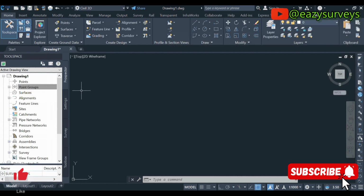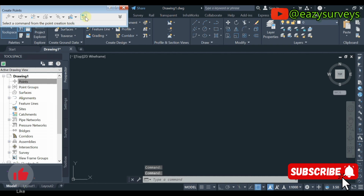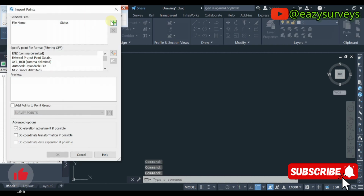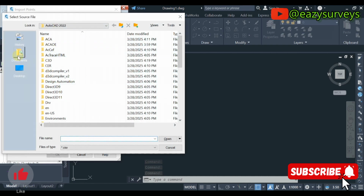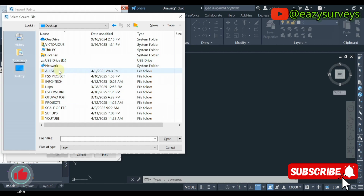Then the next thing is to import your survey points from Excel. So you come to points here, you right click, then you click on create. Then you click on this option. This is the option for import points. You click on that. Then you click on this plus icon. Then you navigate to the folder where you have your Excel data exported. That is the survey data.